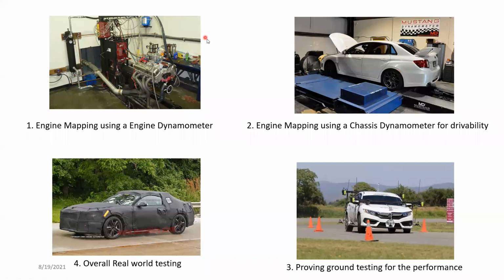Once the base dynamometer graph is placed, this particular engine is put into a vehicle and the mapping is done again. In this case, the vehicle is driven on what we call a chassis dynamometer, where you can drive the vehicle while it measures the power and torque outputs, right? In addition, it's possible to run these continuously according to a driving cycle. Driving cycle means